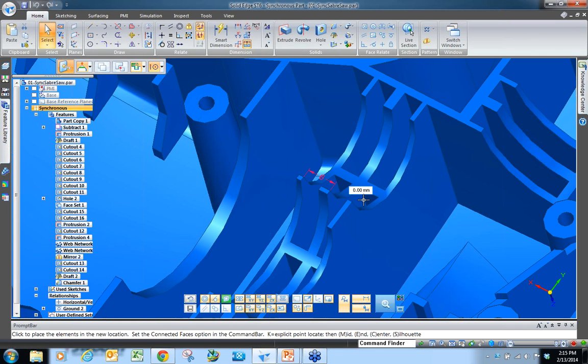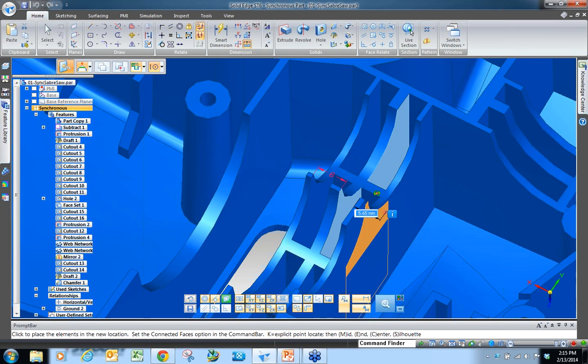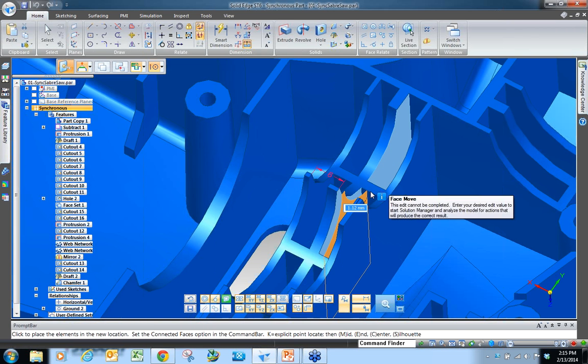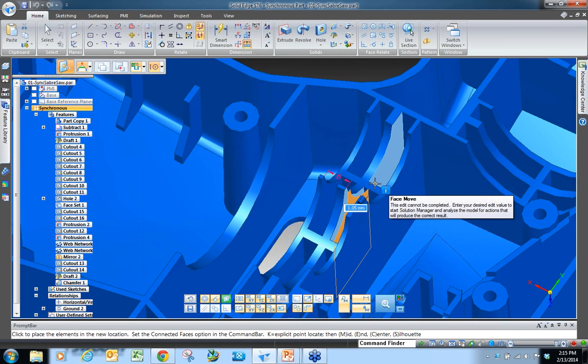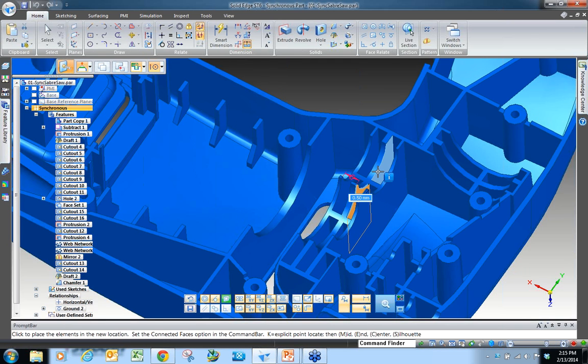And I know some of you that first started out with Solid Edge, when you start trying to stretch faces, you'll end up with this error. It's like, well, how come it's not working? Well, that's what the little I indicates. If you notice, these three faces are all coplanar. That means they're all aligned with each other, and live rules is picking that up.